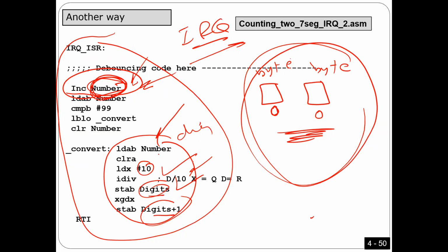So the way I'm going to do increment is, for example, I'm going to increment this one. Sorry, this is the less significant one, so I'm going to start from here. Now there is an event. So I'm going to increment this one, so now I have 1 and I have 0. Good. Then increment this one, 2, 3, until 9. Now I have number 9. You can display number 9. Now when you increment 9, you are going to have 10 here.